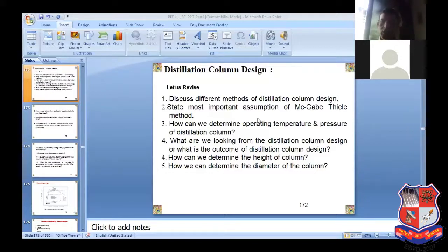So if you continue to boil such a heavy crude fraction at 350 or 400 degrees, degradation starts. Fine. So it is not recommended to heat it at such a high temperature. In that situation, we recommend going for vacuum distillation and vacuum operations, where I can reduce the pressure. If I reduce the pressure, the boiling point is also reduced, and that's why I can separate it out.